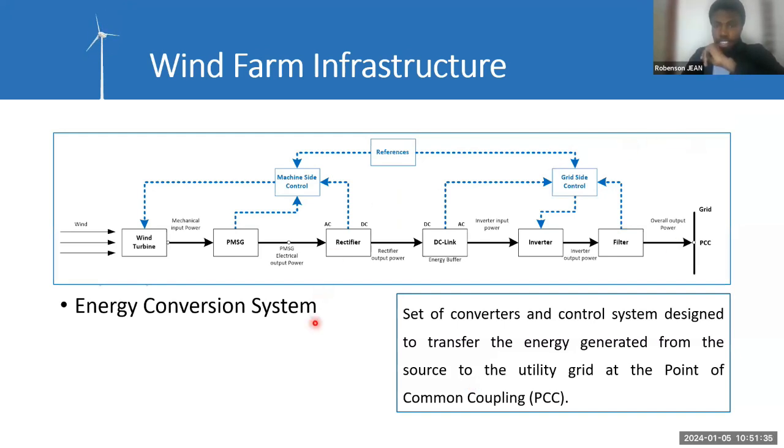But once the electricity is produced, what happens? We have to implement an energy conversion system in order to harvest the energy. So the energy produced by the wind turbine can be made available to the grid or to your house, because even when the wind turbine is producing an alternating current, you cannot directly use this kind of energy due to some parasitic, harmonic currents. So we have to clean this kind of energy in some way.